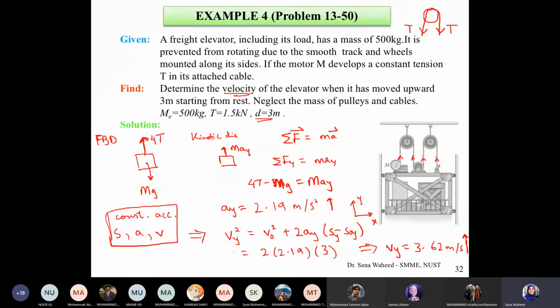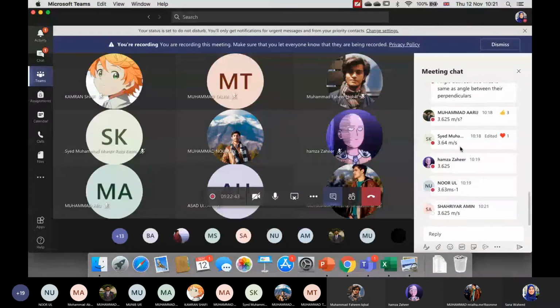So in this case, for my freight elevator, wherever the cable is attached, it's going to be trying to pull it. So over here it's pulling it, here, here, and so on. And I know they will all be equal to T because these are all frictionless pulleys, such that on both sides of a pulley you'd get the same tension. So I have 1, 2, 3, 4 times T acting on the elevator. Right? That was the one main thing to consider. Very good. Good, Shariar.